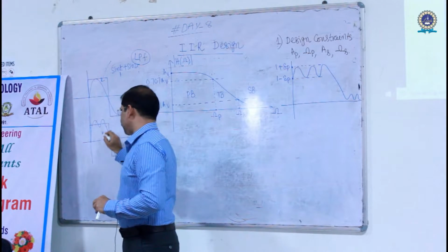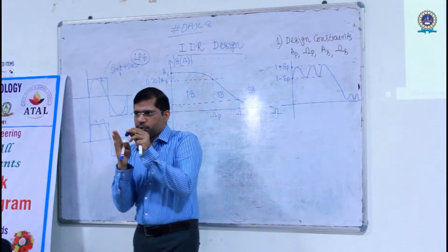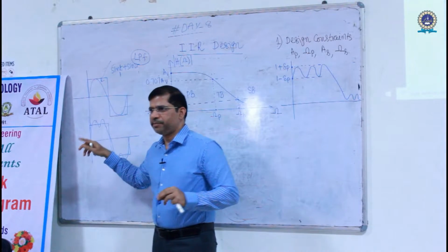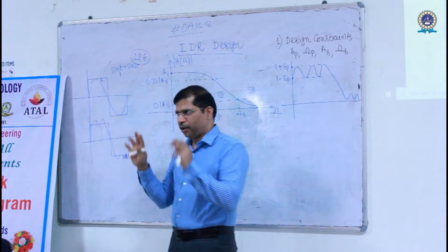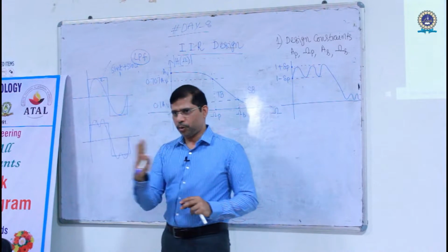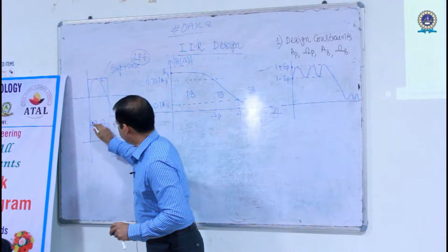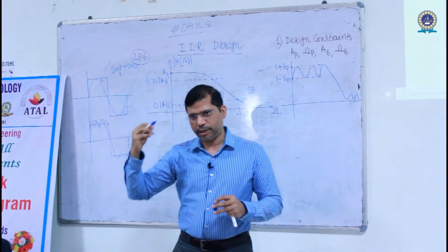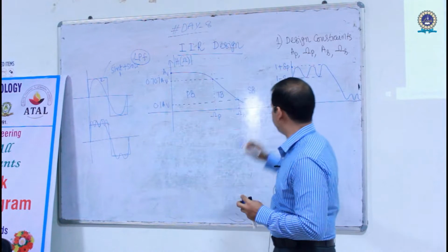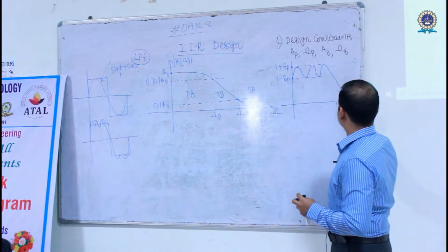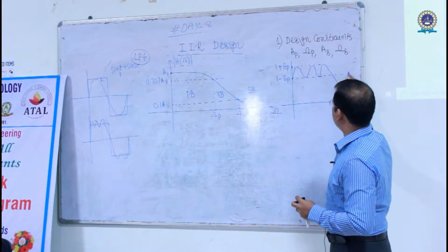If you go like this, then definitely the error will be reduced, minimized compared to this. Now here the error may be 15%. Again you need to ask yourself, can I allow 15% error? Yes or no. Yes means you can replace, otherwise no. No means again you have to go for 3 harmonics or n harmonics. That's what Gibbs proposed a long time back, and we call it the Gibbs phenomenon. You need to observe that point here. Here I have taken 3 harmonics. Those harmonics are now called ripples.